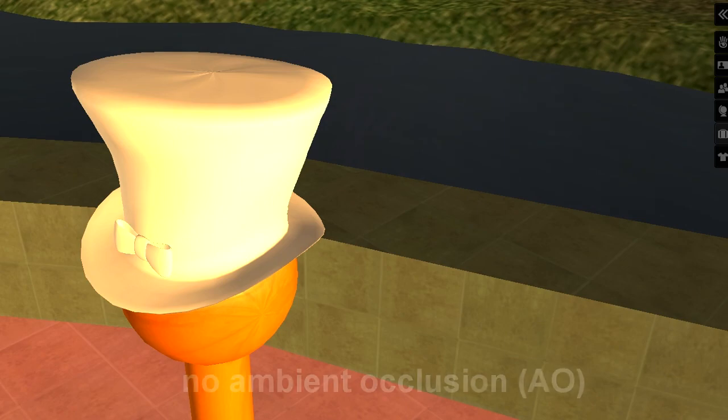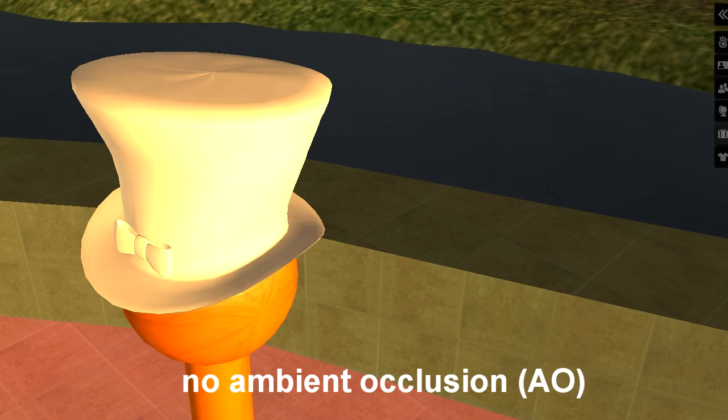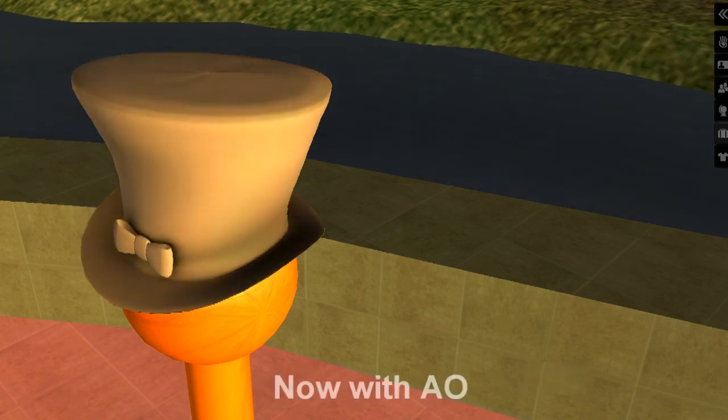Consequently, when a point is fully occluded, the pixel value gets black. When it is not at all occluded, then it gets white. As an example, a flat surface will be rendered gray because the object self-occludes half of the viewing sphere. Although ambient occlusion is an artificial calculation, it helps us to make an object look more realistic, and since it is not depending on the camera position, it can safely be baked into a texture.